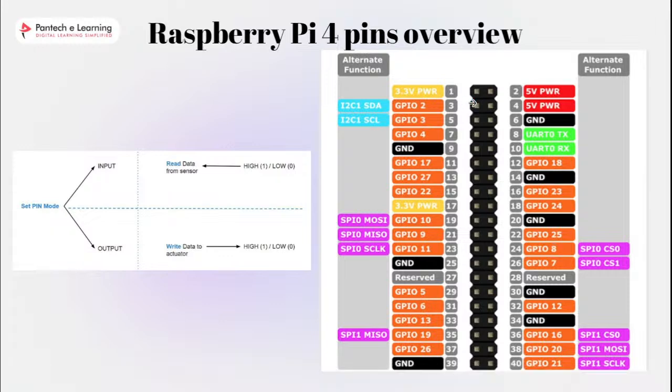Okay, the ground is very useful for making a common reference between all components in your circuit. Always remember to connect all components to the ground. If you connect two circuits together, put a wire between both grounds to make it common.